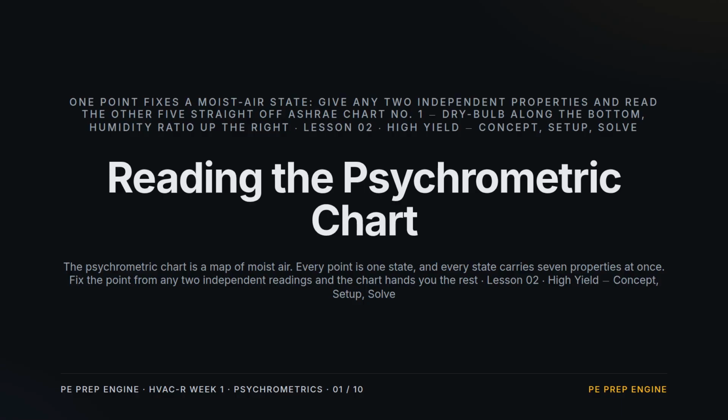Week 1, Lesson 2, Reading the Psychrometric Chart. This is the visual keystone of psychrometrics. The chart is a map of moist air. Every point is a state, and every state carries 7 properties at once. Fix the point from any 2 independent readings, and the chart gives you the rest. We'll learn the axes, the families of lines, then plot a state and read it.